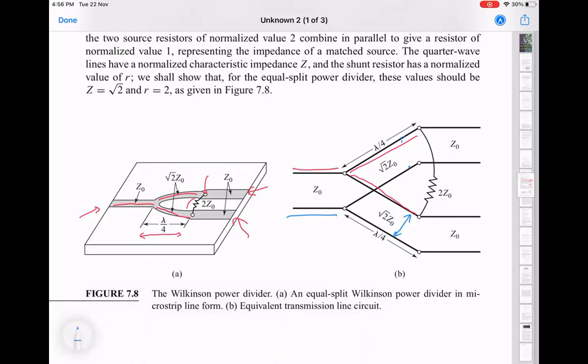And then you see that this resistor here is connected between this point and this point, which is basically where the transmission line is changing back to being 50 ohms, which is Z0, right? Again, on the center pin. So we have assumed this to be the signal, and this, let's say, to be ground. So it's between the two signal ports on this side and this side, which is the same as this guy here. Okay.